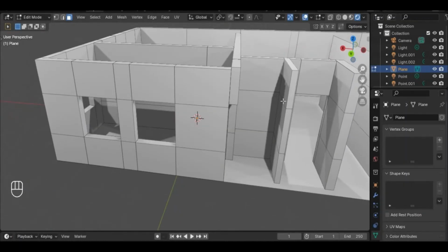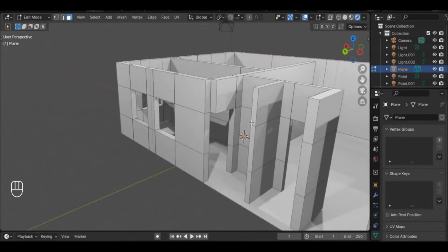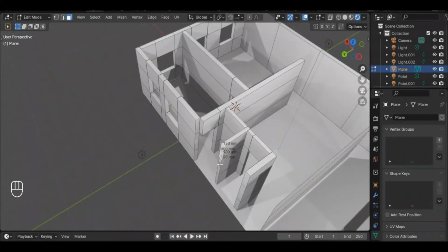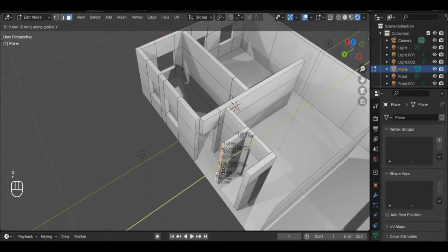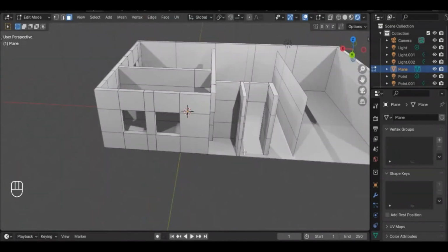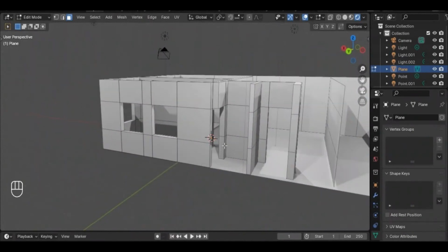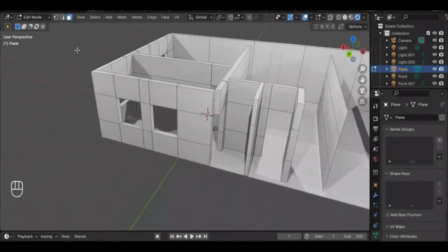So now we have to decide where we want to put our window. But it's always economical to allow the window to not overlap really, and also let them overlap the wall in between. You can make them overlap the wall in between. So let's try to make this overlap the wall in between. Which means if we are doing that, we need to shift this forward to make up for the overlap in between. So we shift it by 225, so that it's going to meet the boundary of our house or foundation. So now let's try to create our window.